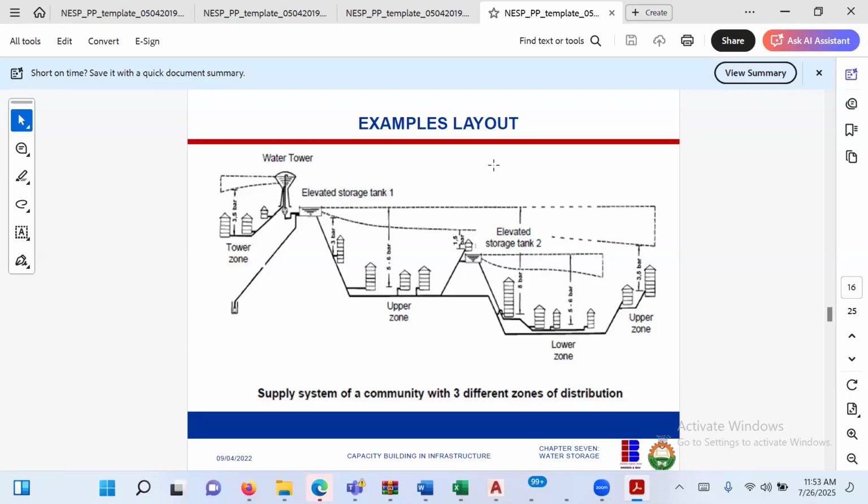So in this case, you need to split this water into different zones. And that's why we have zone 1, zone 2, zone 3. So you position the water system, the wells, where they optimize the zoning formula. Because when you come to a system or a vicinity, a place like Plateau State, where different people are living in mountainous places, elevation, you need to allocate your tank, size your tank, in such a way that buildings that share the same pressure will use a particular tank. So you can have upper pressure area, lower pressure area, medium pressure area, or you simply name them tank 1, tank 2, tank 3, tank 4.